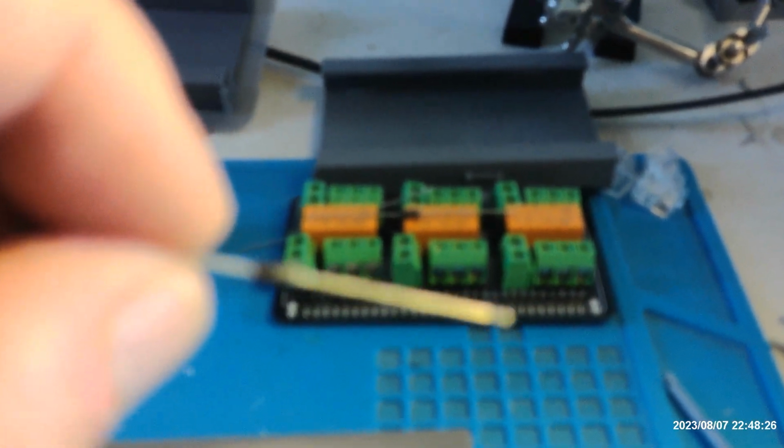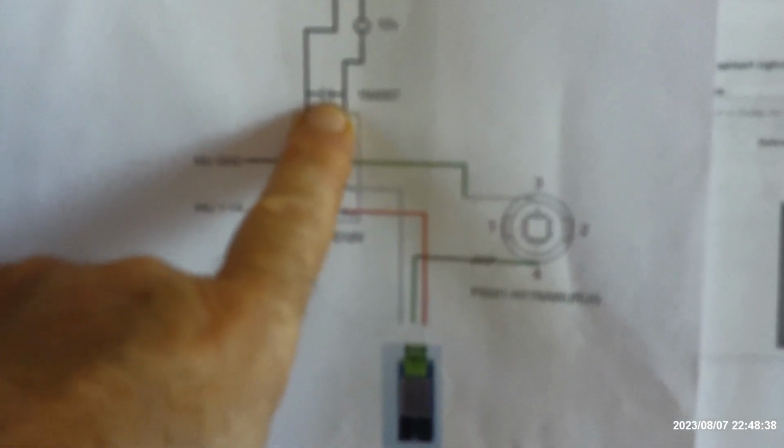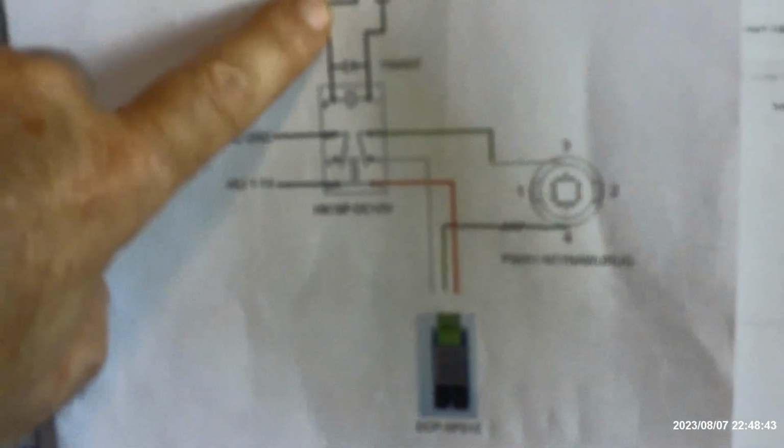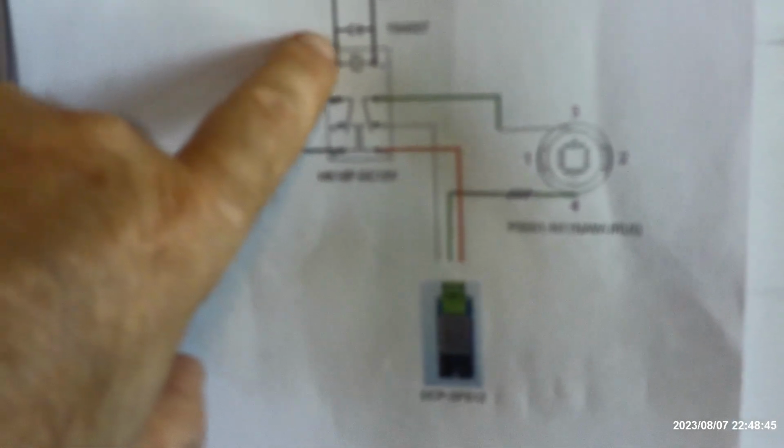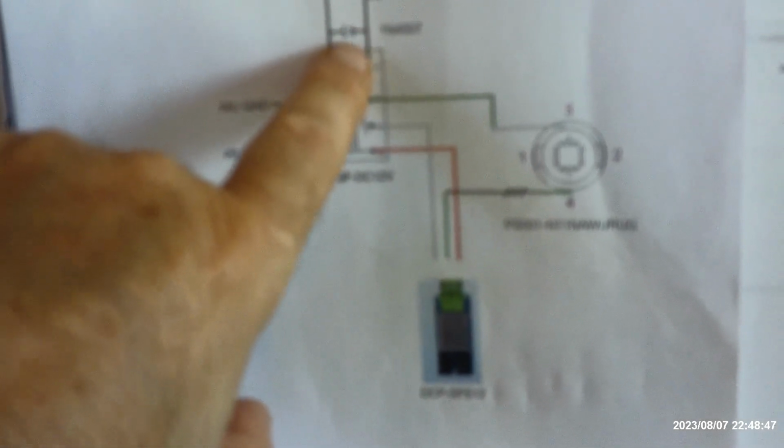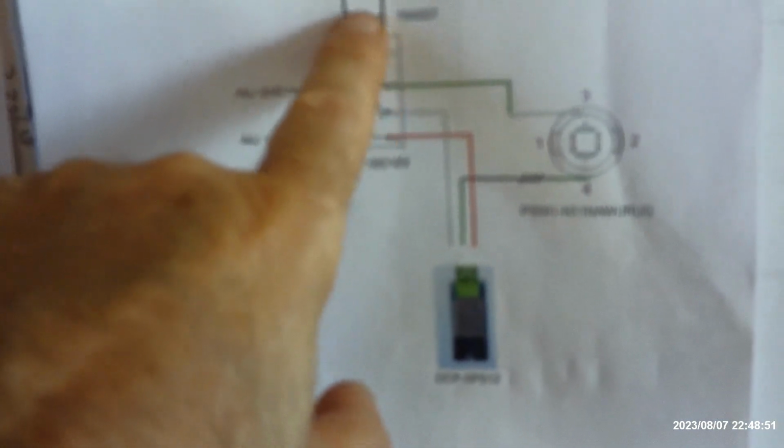Now it's the background, but there is a gray stripe around it, and that's on the diagram here. We see the diode, and that gray stripe is represented by that. So what that does is when current is coming down here, it won't go back through here. This stops that from happening.